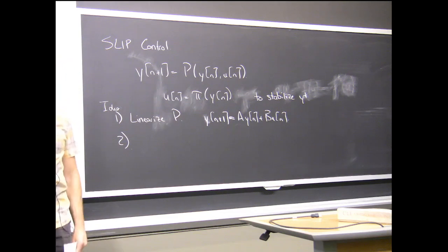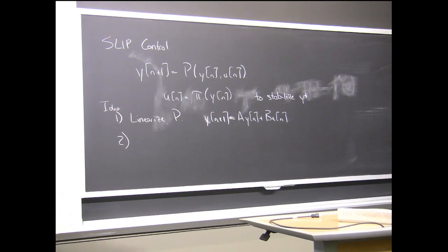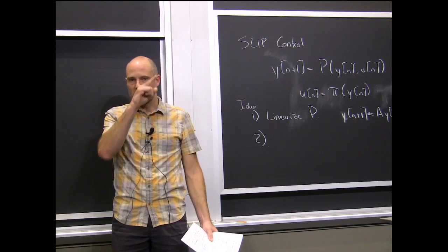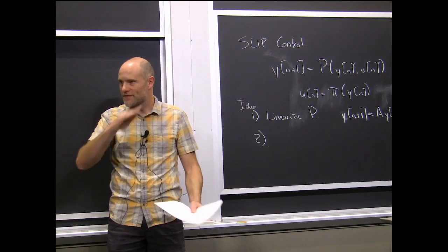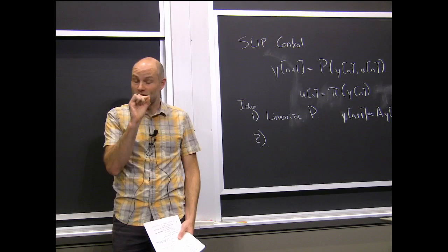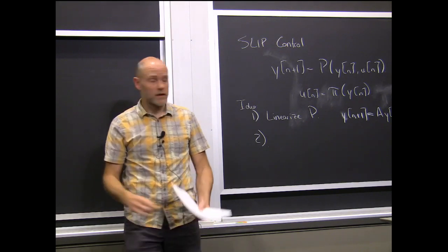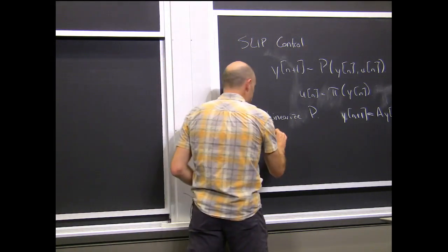But there's actually something you can do in these systems, and it's possible in any discrete system, that's even stronger than LQR. In a continuous time system, if you want to get to the origin, maybe you try to do it exponentially fast. Whereas a discrete time system can jump directly to the origin, in exactly one step, okay? So that would be called deadbeat control.